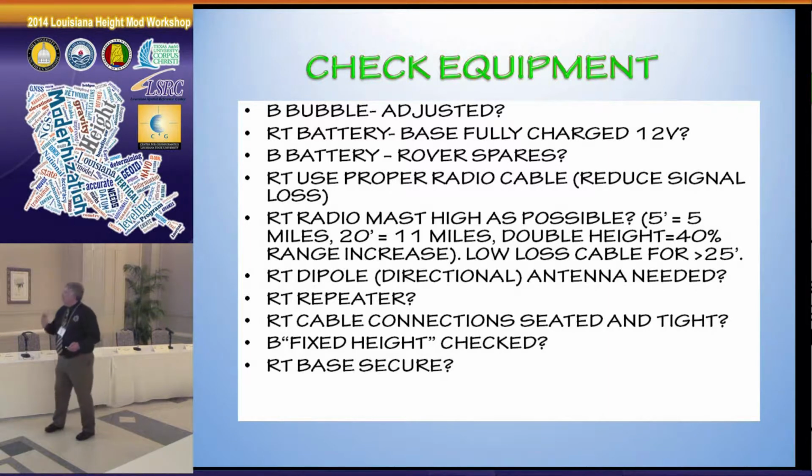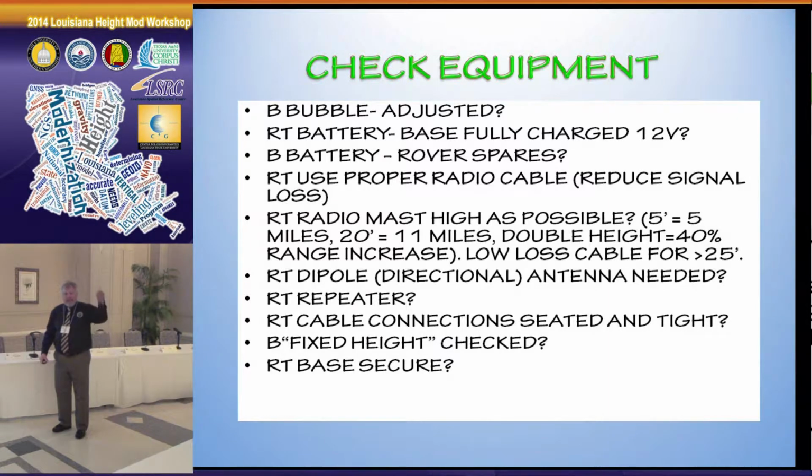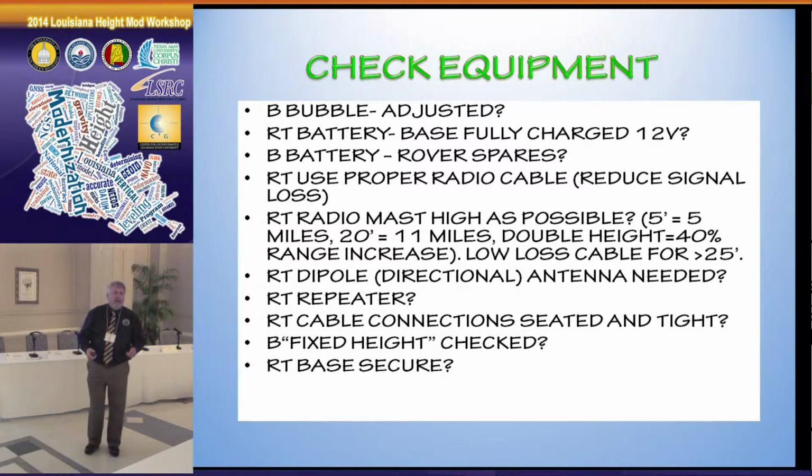And you can't really go more than 25 feet because then you need a low loss cable. You lose some signal by attenuation going down that cable. But if you can elevate your radio antenna, you're using UHF radios, which a lot of us still do, and there's areas where I come from where you don't have cell coverage, that you need to do something.